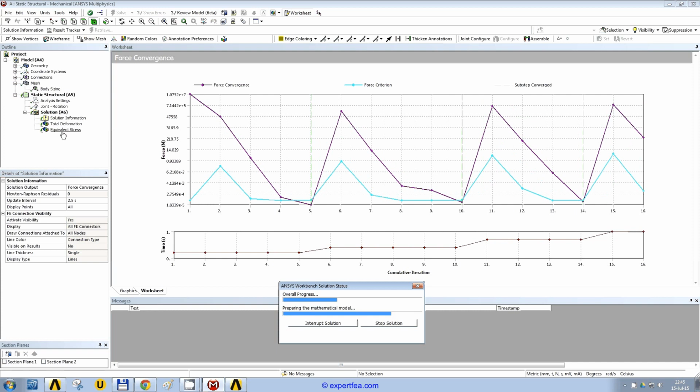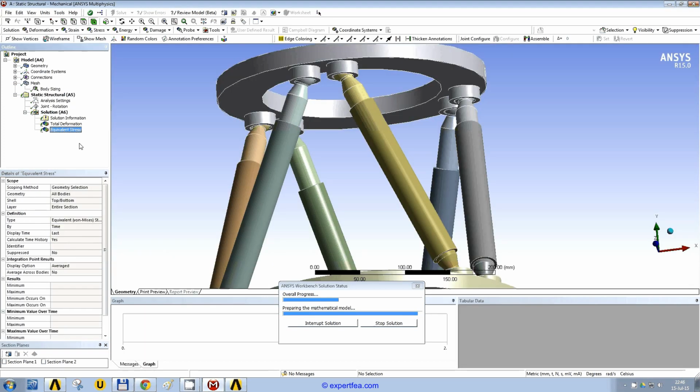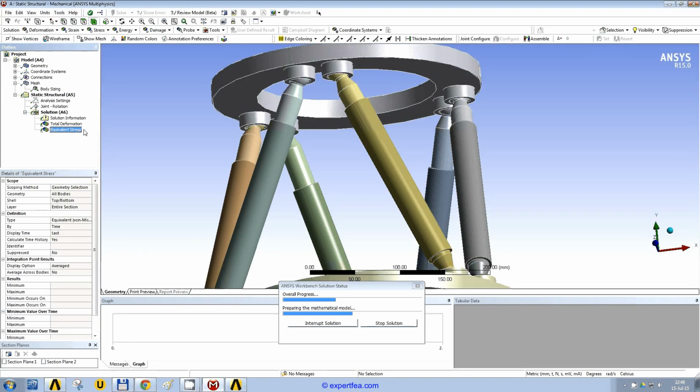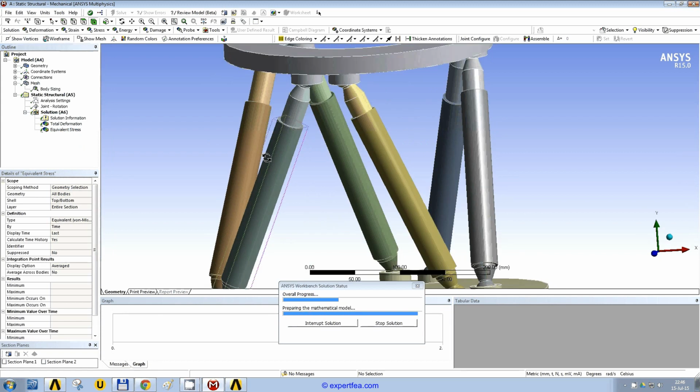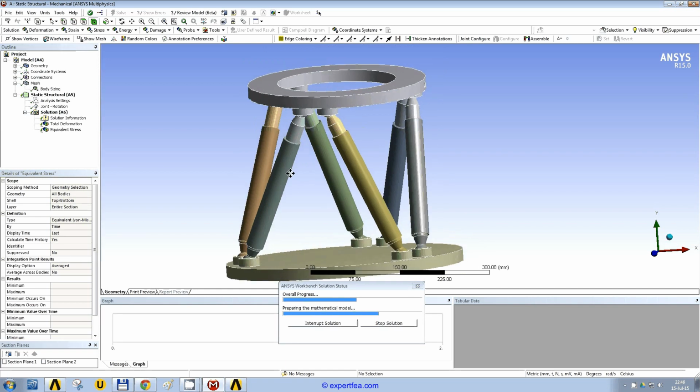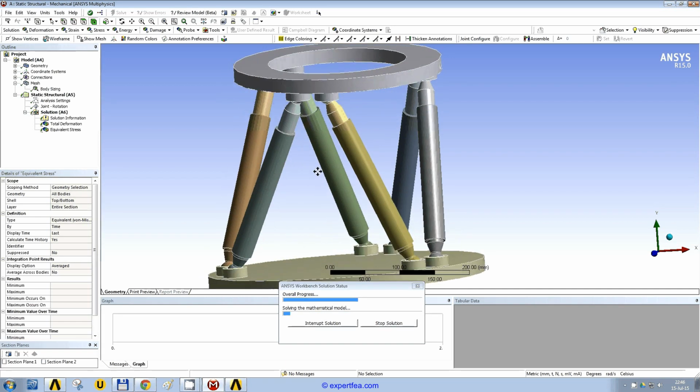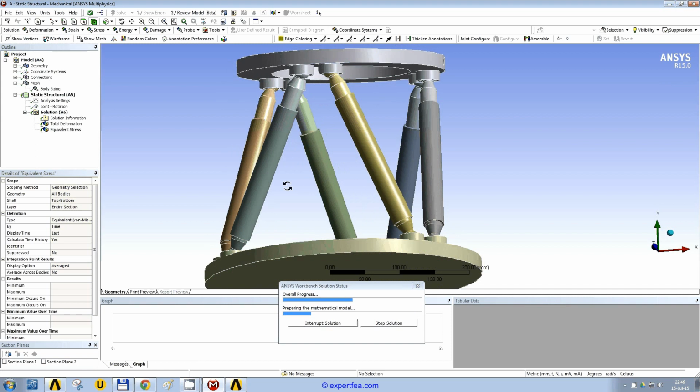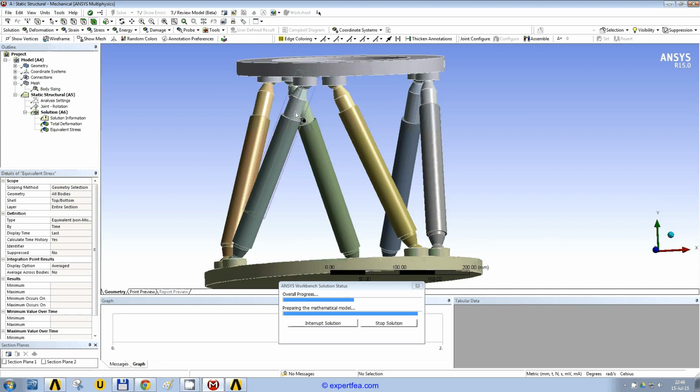Regarding the lack of stress, you remember the small values of stress, almost zero. It's because we do not have a gravity defined. So let's say the outer tubes do not rest on the inner rods, so there is no touching because of translational joints.